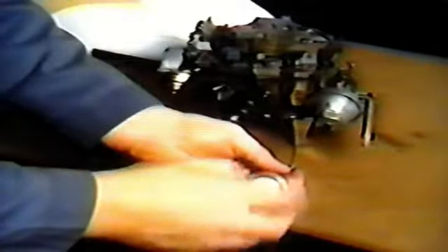Setting mixture screws to factory specs is a fairly recent development. In the old days, you might just back them out to 3 turns and balance them with the idle adjustment. But since 1981, it's been necessary to be more cautious because the correct setting may be anywhere from 1.5 to 6 turns. If you're off by even a couple of turns, you could be starting out at either too rich or too lean, and that means trouble right from the beginning. The factory specs for this 1983 carburetor call for 3.5 turns, so you'll need to lightly seat and back out 3.5 turns. Now the carb is balanced, and we're ready to move on to the next step.